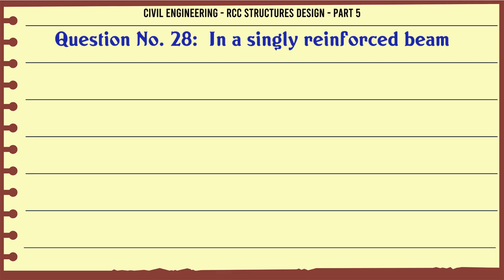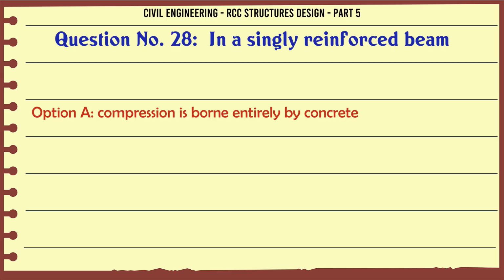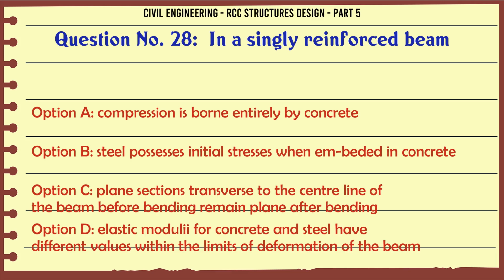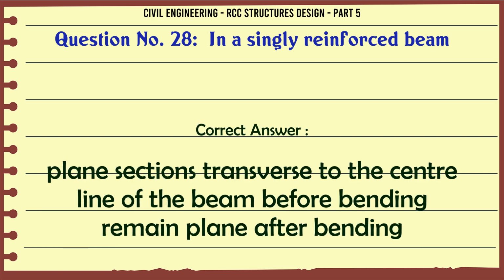In a singly reinforced beam, A. compression is borne entirely by concrete. B. Steel possesses initial stresses when embedded in concrete. C. Plane sections transverse to the center line of the beam before bending remain plane after bending. D. Elastic moduli for concrete and steel have different values within the limits of deformation of the beam. The correct answer is plane sections transverse to the center line of the beam before bending remain plane after bending.